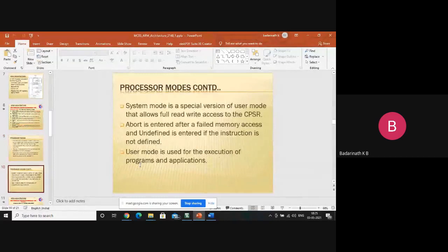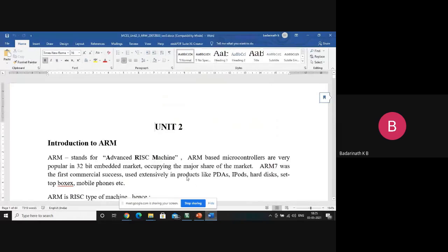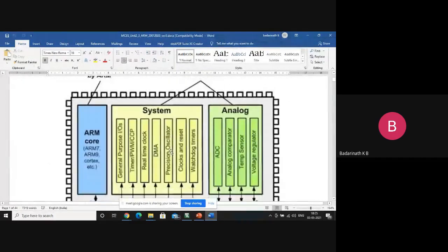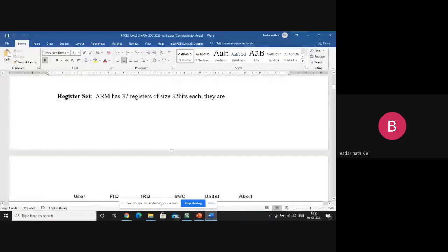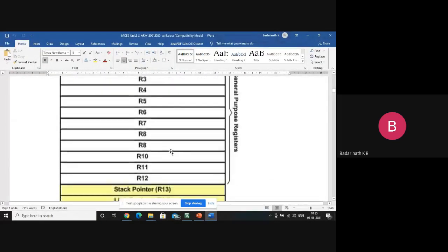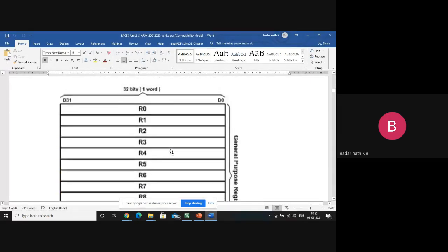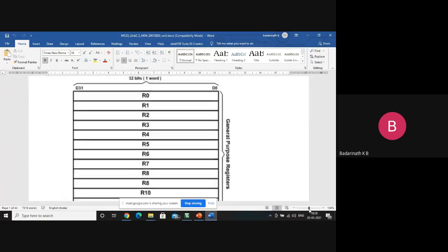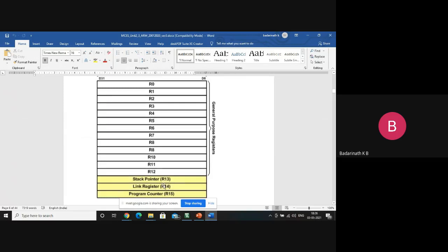That is also something we have discussed in detail. The ARM architecture basically supports 16 general purpose registers for a programmer. Those registers are called R0 to R15 and are present inside the microcontroller. Of these registers R0 to R15, we discussed that 3 have a special function. It is left to the programmer whether to use that function or to use them as general purpose registers.